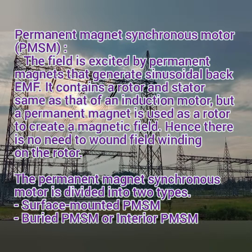Then the next topic is the permanent magnet synchronous motor. The field is excited by a permanent magnet that generates a sinusoidal back EMF. So it contains a rotor and stator like an induction motor, but a permanent magnet is placed in the rotor to create a magnetic field. Hence, there is no need to wind a field winding on the rotor. So this permanent magnet is responsible for creating the magnetic field.